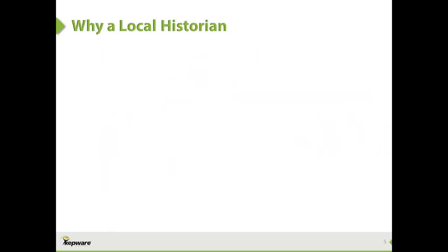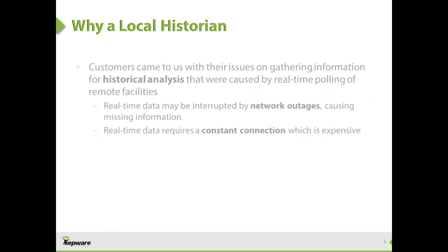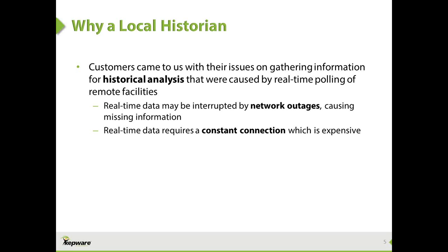To understand why transferring buffered data is attractive versus transferring real-time data, we can look at what our customers were describing as far as issues. Maybe they had missing information in their corporate historians due to communication issues with that remote site. By transferring the historical records instead of real-time data, the user doesn't need to worry about constantly maintaining a high-quality real-time connection, which can be inefficient and expensive.